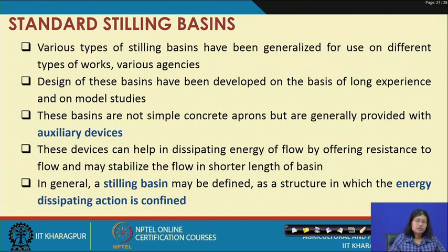Now, the kinds of stilling basin. Various kinds of stilling basins have been generalized for use on different types of work and various agencies. The design of these basins has been developed on the basis of long experience and model studies. These basins are not a simple concrete apron, but are generally provided with auxiliary devices. These devices can help in dissipating the energy of flow by offering resistance to flow, and may stabilize the flow in a shorter length of the basin.